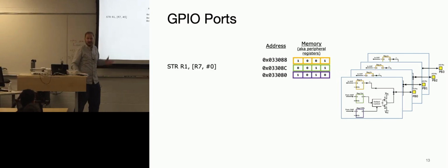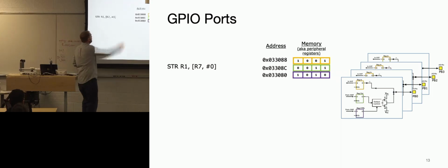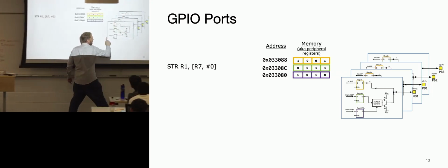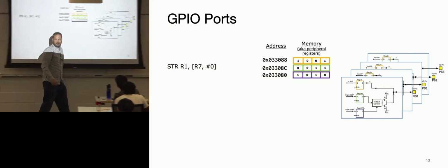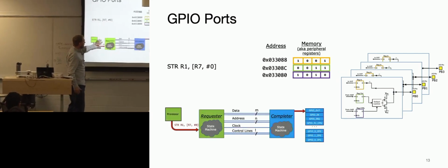And you know how to do that. You guys are great at it now. You do loads and stores. Loads and stores manipulate bits. I'm gonna do loads and stores, I'm gonna manipulate these bits, and these pins are gonna go high or low. And how are you gonna do that? What's the mechanism? Well, that's what we did learning about the bus.